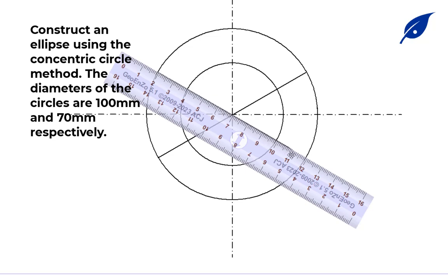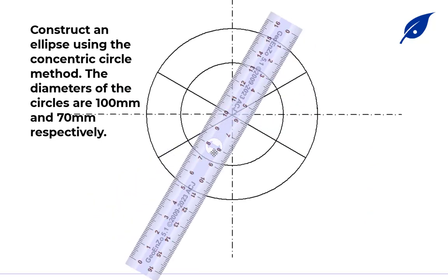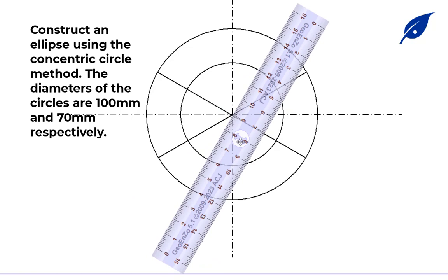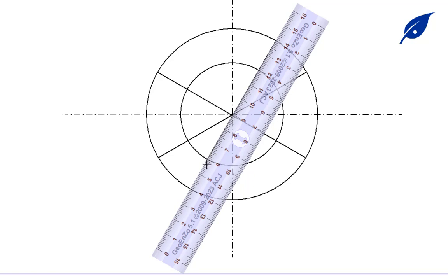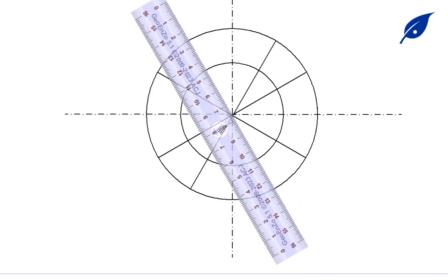So after getting this side, I'm going to select the 60° set square. So you align it to the center of the circles this way, and draw your line to divide it. We also flip our set square to the other side, the 60° set square to the other side to get this. So finally we have our circles divided into 12 equal parts.